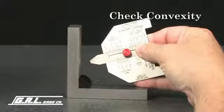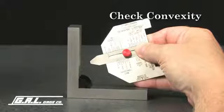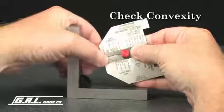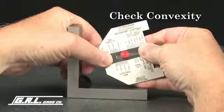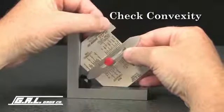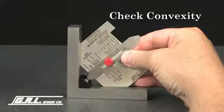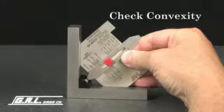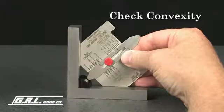To check convexity, first verify the fillet weld size from specifications. Again, in this case, a half-inch fillet weld is required. On the gauge, use the max convexity scale and set the slide to a half-inch. Now, place the gauge so that the 45-degree bevel rests squarely on the adjoining surfaces. In this example, the weld is within the permissible maximum convexity. Additional weld could possibly compromise the structural strength and integrity of the weld.